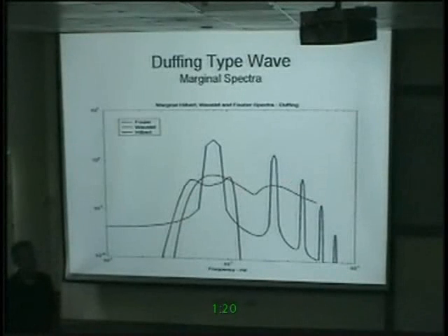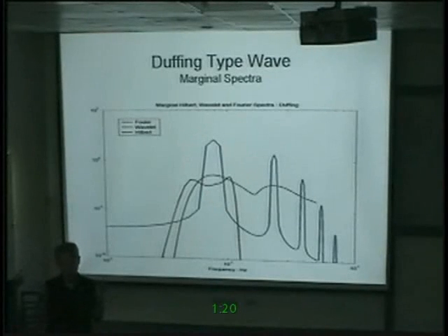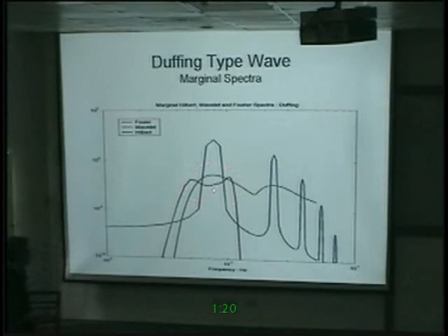What will Hilbert give you? Hilbert will give you a frequency here, and the frequency wobbles back and forth. And that back and forth wobble represents the frequency modulation. And this is very, very important, and also very important for future applications. Any time the fundamental frequency becomes broadened, that means nonlinear. That means intra-wave frequency modulation. And that is the same thing as harmonic distortion.